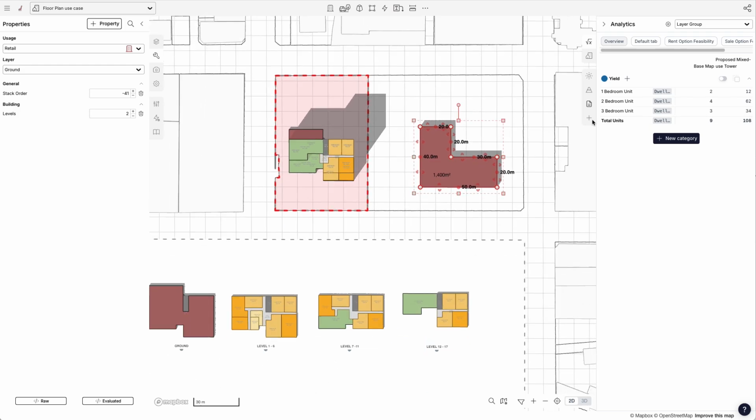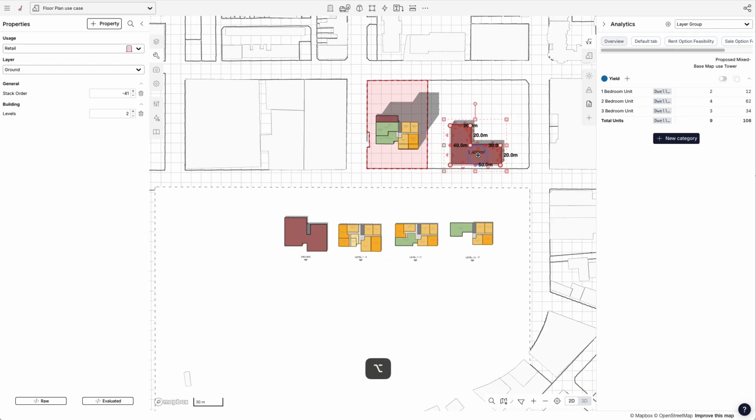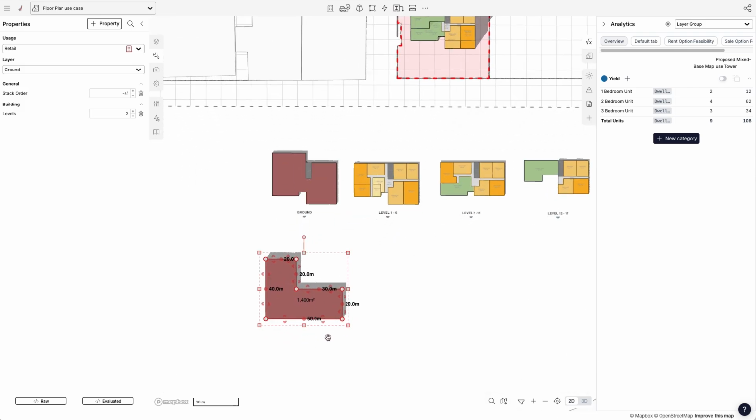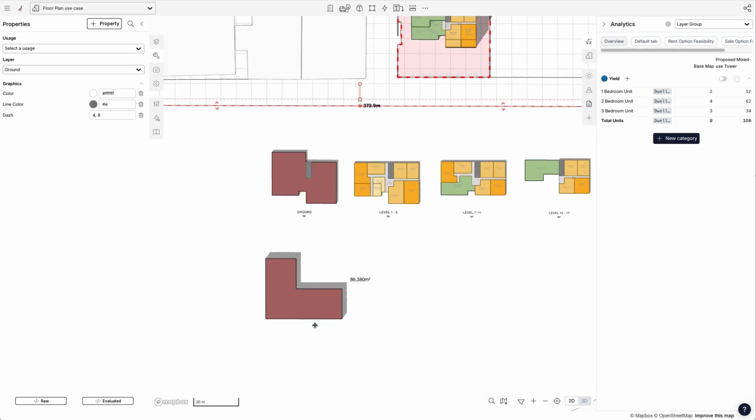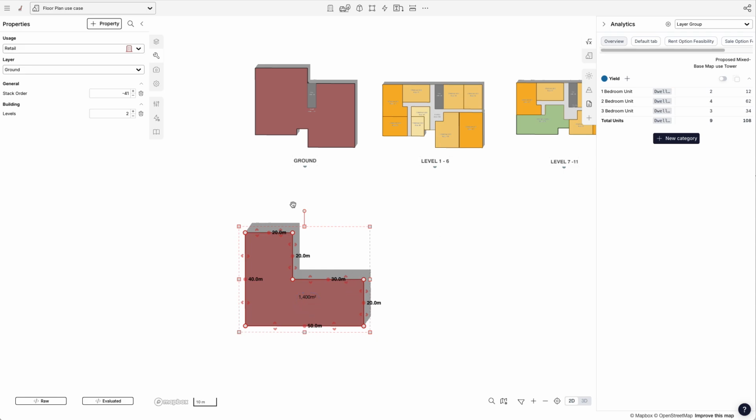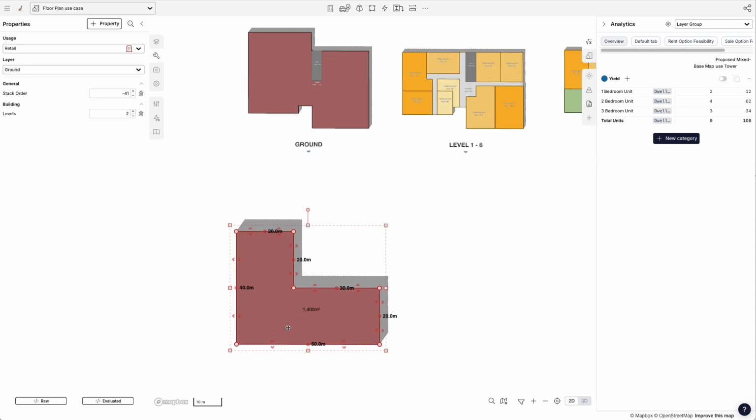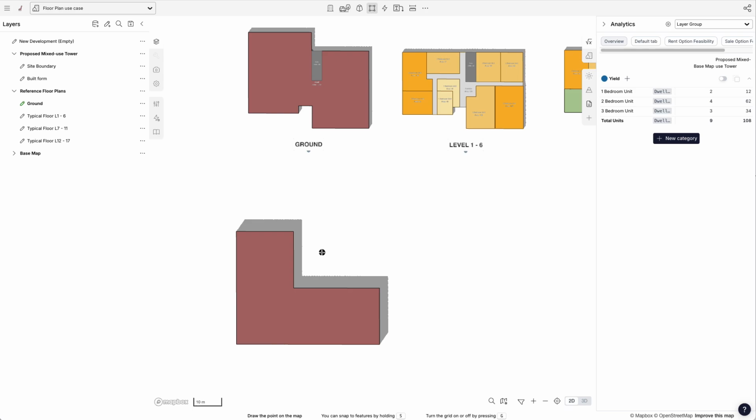So what I'm going to do is actually drag this off my floor plan, because I'm going to use this as my new referenced ground floor plan. And I need to add one more element in order to make that a group. So, and what we need there is a point. So if I navigate up to the basic shape tools, grab the point, and this is going to be my reference point. So wherever I put it is where I'm going to be able to move this geometry and sort of stack it from. So I'm just going to grab the corner here.